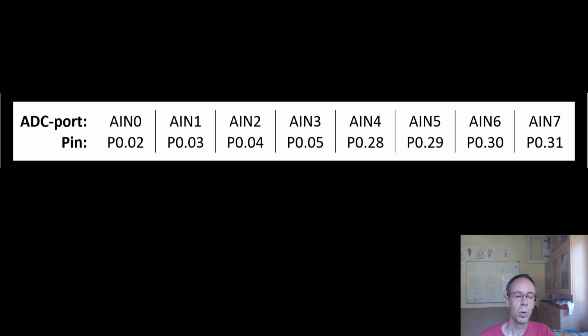Our nRF52840 microcontroller has altogether 8 channels, so we can make 8 different analog digital conversions. They will not be done in parallel, they will be done in a row with a multiplexer, but we will not realize this. We can use 8 of them, and for this we also have 8 ports or pins. We have to differentiate them from channels. It's not the same, and we can choose which port will be connected with which channel.